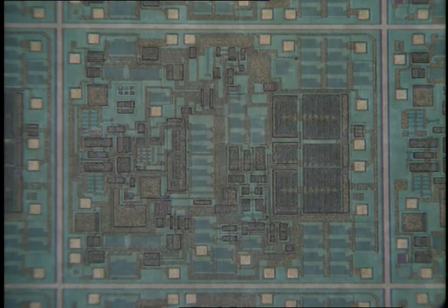Finally, here's a more recent example, a dual-channel, low-noise, variable gain amplifier for ultrasound applications. Its principle of operation doesn't rely directly on translinear behavior of devices, but the analysis of its special behavior is facilitated by knowing that the bipolar devices used to achieve the variable gain do in fact exhibit this unique proportionality of transconductance to collector current.